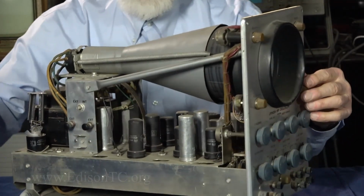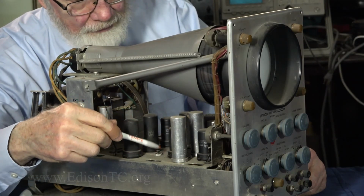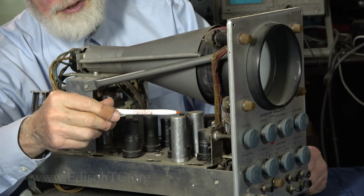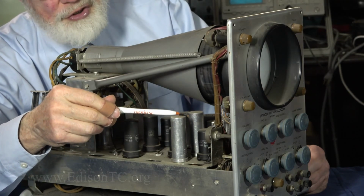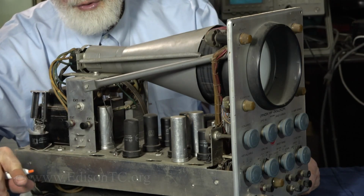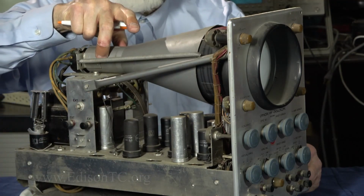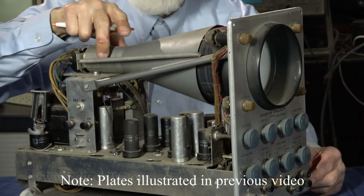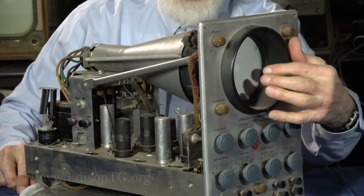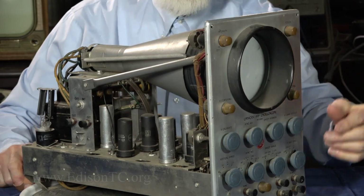So what we do is there's an amplifier. These are from the 1940s, so it was a vacuum tube amplifier that would amplify both the voltage that you wanted to measure and also would generate a time base. The time base was a rising voltage, a straight line rising voltage, and when you put that across the back side, the deflection plates, then you would have the beam go across the side from side to side. So if you had a sine wave, it would go up and down as it's going across.